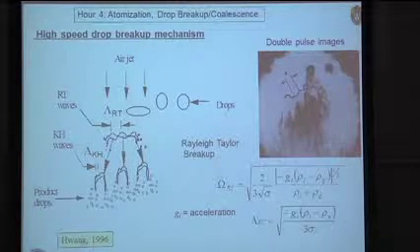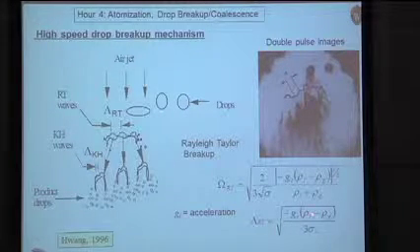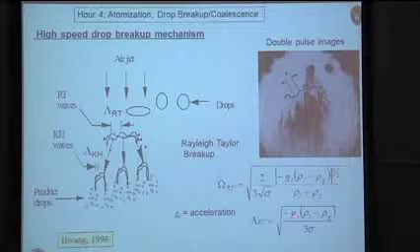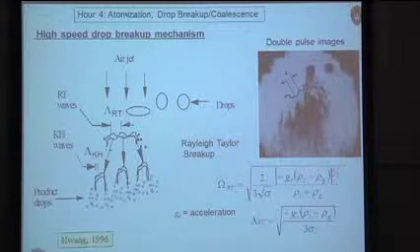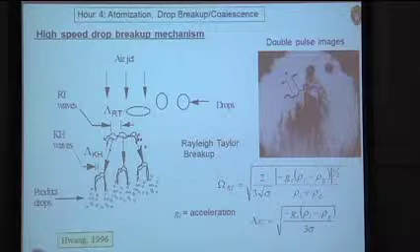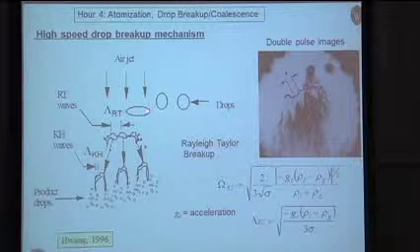The Rayleigh-Taylor theory predicts the wavelength of those unstable waves in terms of the acceleration, which would be a negative number in this context, and the surface tension, and also the growth rate of those instabilities. So the drop stream comes in here, is hit by the air, the droplets flatten because of that dynamic pressure effect.